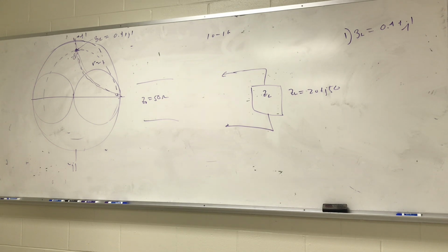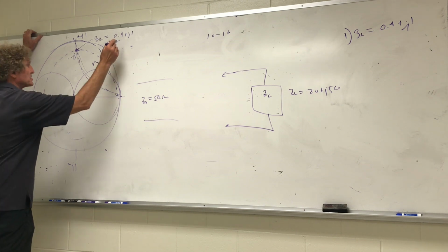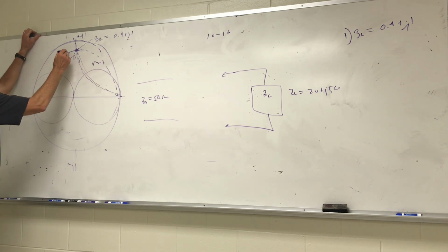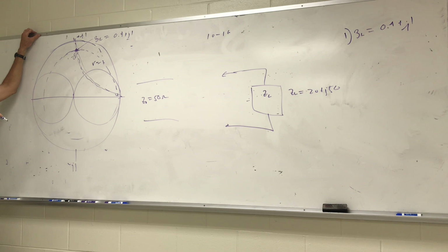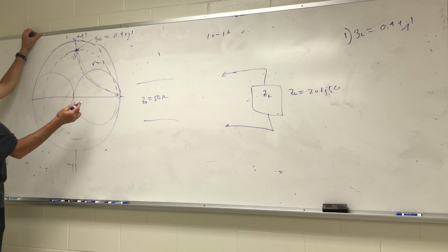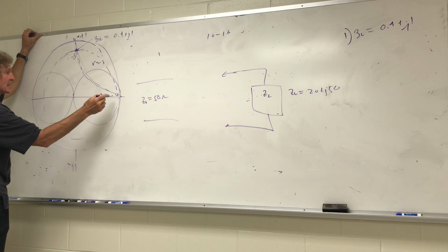Now first make sure you can see that point. Okay, that's the first point. Now, what are your options? Remember, this has got a J of 1. If we add impedance, which would be adding an inductance, positive inductance, or sorry, this is plus J, we would have to add a negative impedance, which would be a series capacitor.